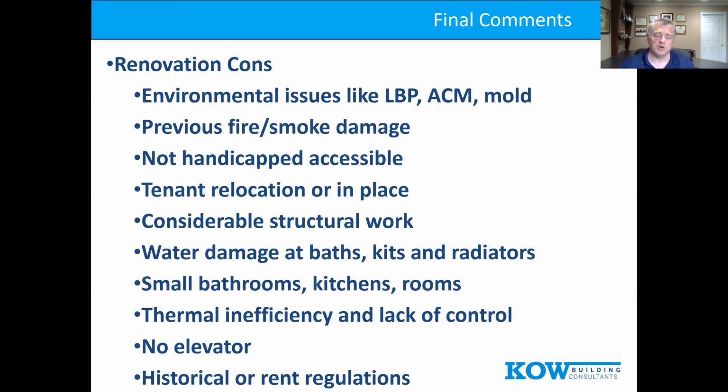Another con, considerable structural work. Obviously, fire, smoke, water, notches, etc. We've seen buildings that have been vacant for years and years and years, and it's fine. The moment that roof leaks, it's a house of cards. Because now water comes in, now birds come in, and now it's just a matter of time. So if you have a building that's had real disrepair or has been boarded up or abandoned for years or has been neglected, considerable structural work. Not cheap and takes time.